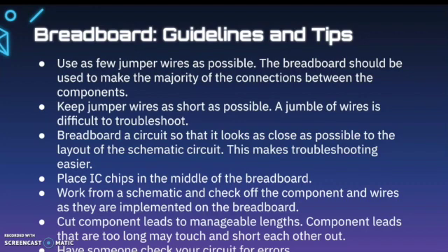You want to keep your jumper wires as short as possible. A jumble of wires is difficult to troubleshoot. The same thing goes in Tinkercad. Keeping the components closer together on the breadboard can be easier to see where your circuit is going. If we have a lot of components, we're going to need to spread out across the breadboard in order to be able to see things, but we want to make sure that we're staying as organized as possible.